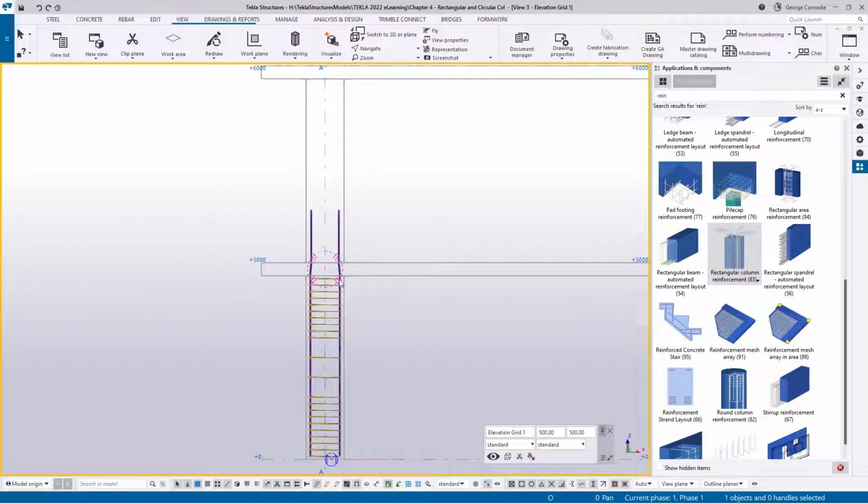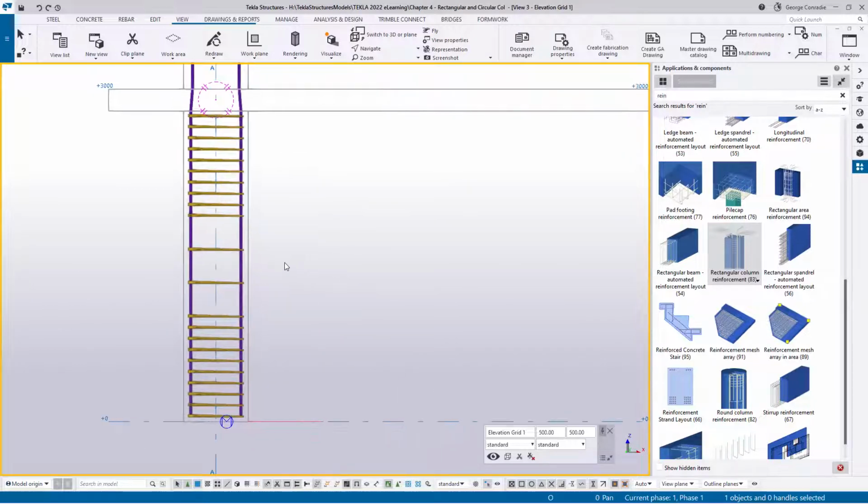And then for the elevation, the norm, definitely here in Australia, is that over your lap length, if you can imagine you've got your starter bars coming out of your foundations in here, you have these stirrups spaced at half the spacing of the normal stirrups, the ones in the middle here. And then on the top, they normally have 4, 3, or 2 sets of ligatures at 50mm spacing or so. So we'll do something like that.